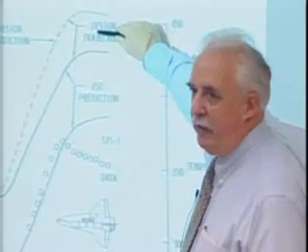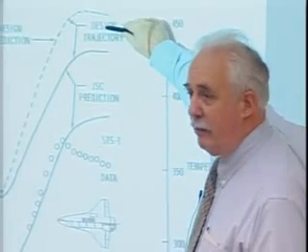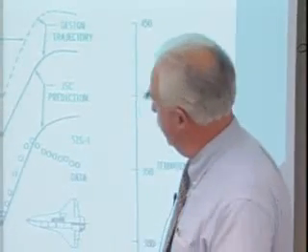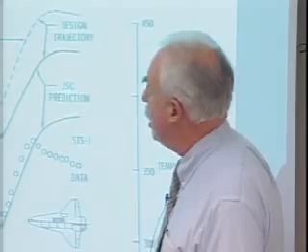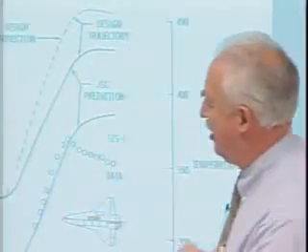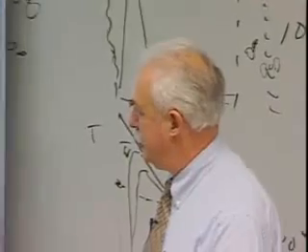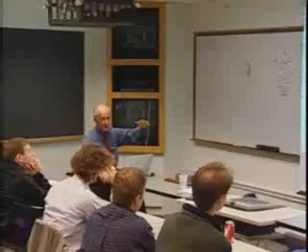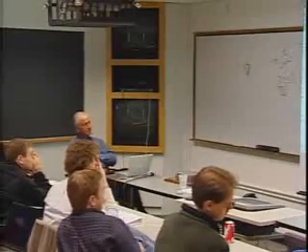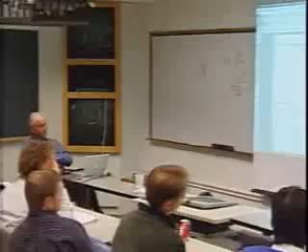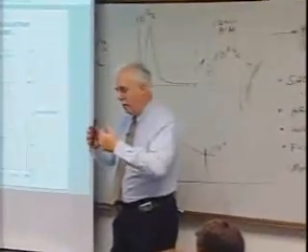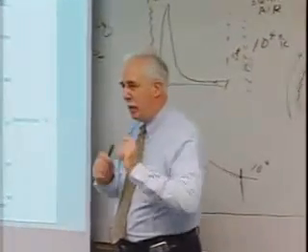Our design condition was we do not exceed 350 degrees Fahrenheit if we want to have 100 flight life with this aluminum. Aluminum is great stuff because it's a good conductor, but it's low temperature, it expands, has some other... Bond line, that means that the bottom, just so that everybody understands. Yes, thank you. Those temperatures are much lower than you see on the surface of the tiles. That's after the heat has diffused. Right. I think Tom probably talked about the SIP, the strain isolation pad. I'm sure he did. This is after you diffuse through the tiles and through the RTV bonds through the SIP. This is the actual aluminum temperature.